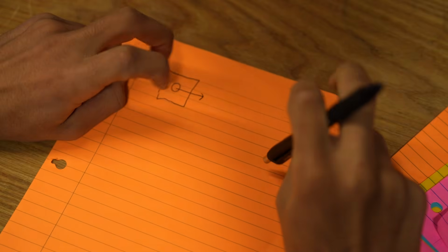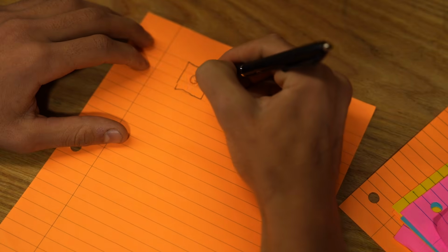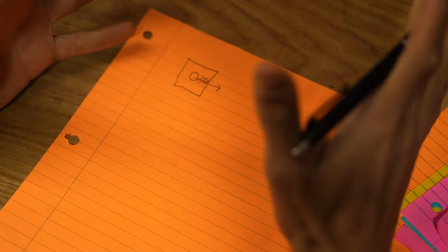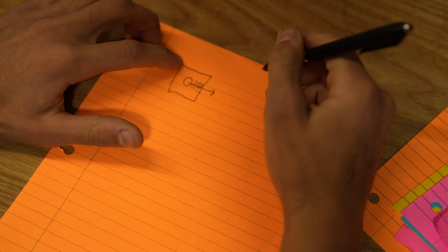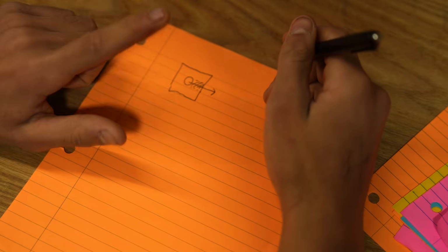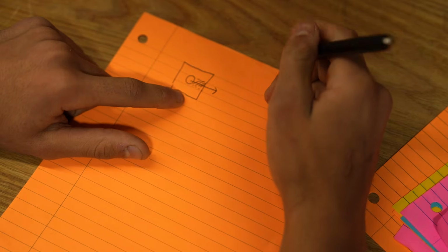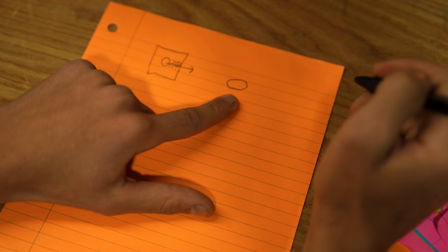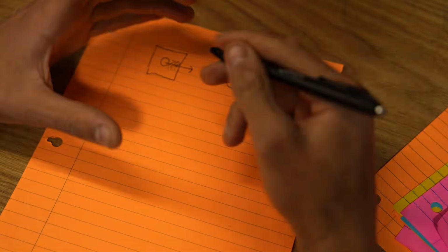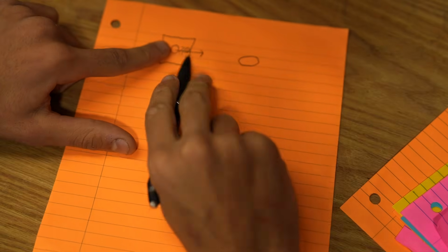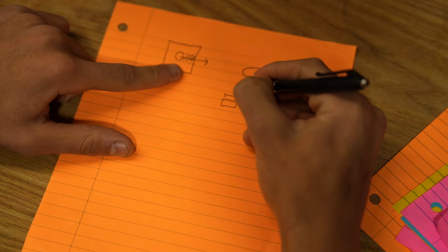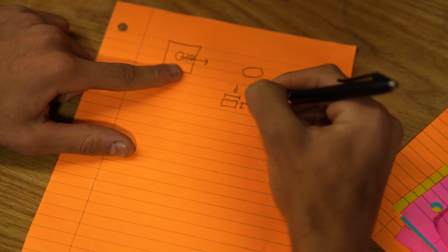The projected area of that bolt, this shaded area right here, has to be able to hold the load of that bolt. In particular, when using steel hardware and something weaker, you can get an ovalization failure of your bolt, which I'm sure you've seen before, when you're pulling too hard and the material can't resist you. So the area of that cross section is the diameter of your bolt and the thickness of your material.